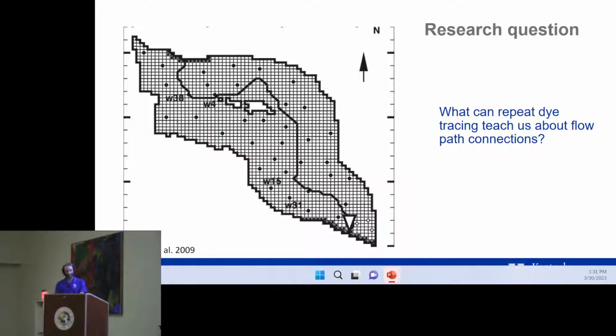With this concept, this model here, you have a river that's flowing through here. If you get a flood pulse moving through this river, you can actually monitor that flood pulse, that wave, as it migrates away from that river through the subsurface, and you can see this wave propagate through monitoring wells and use that to really understand flow path dynamics in the subsurface.